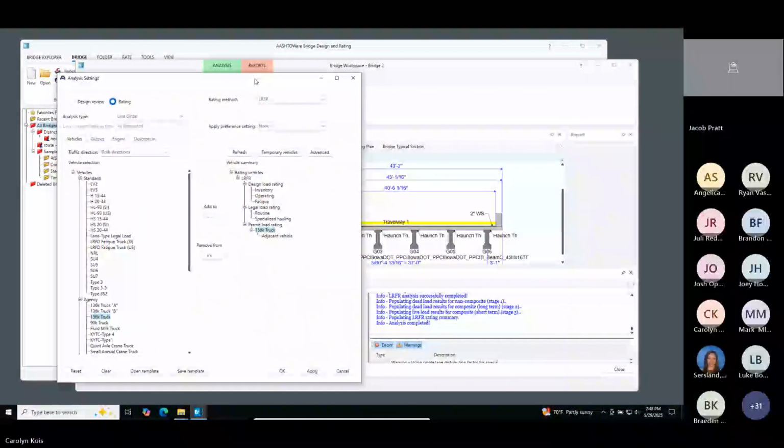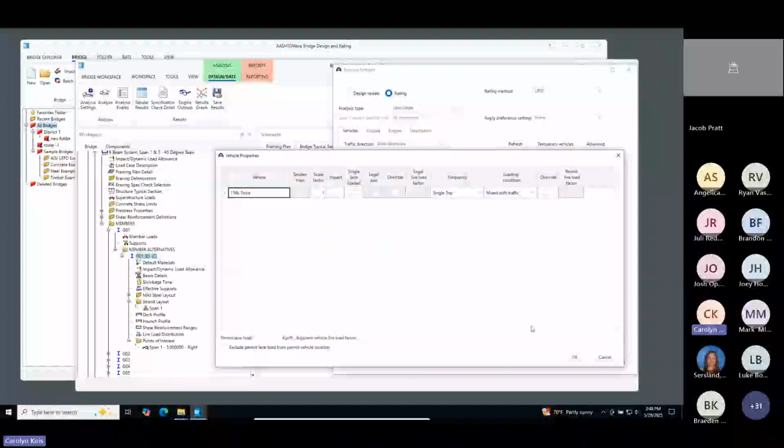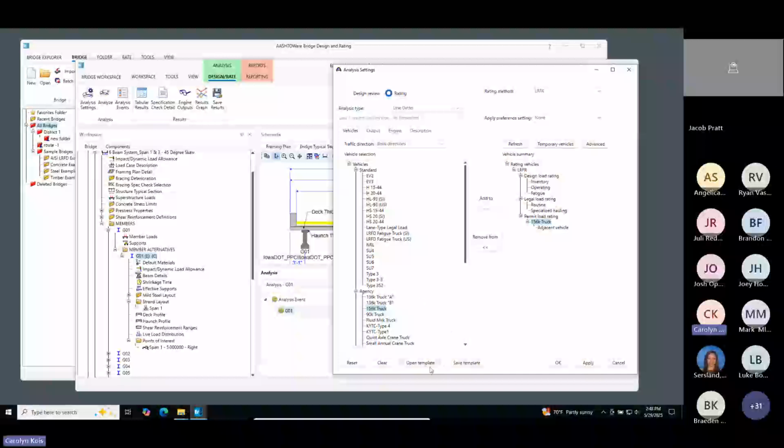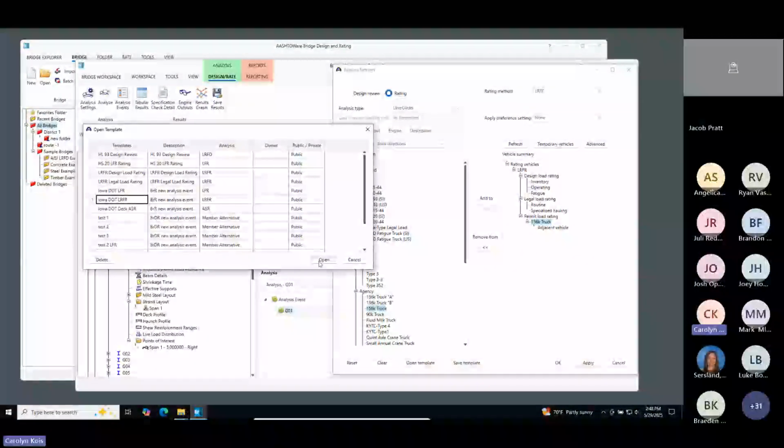It will still consider this whole travelway. So if you did want to restrict it to part of the travelway, you could either adjust the travelway, use stripe lanes, or non-standard gauge. I know that's a whole other topic, but this advanced options tab here allows you to make changes to how those vehicles are configured.